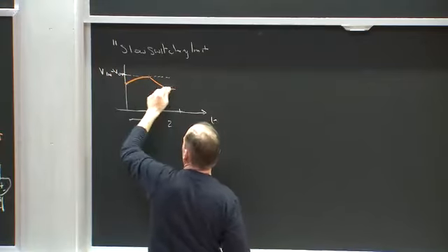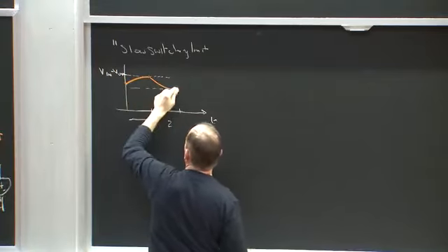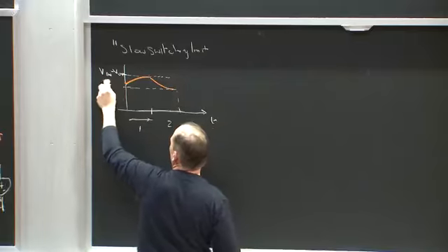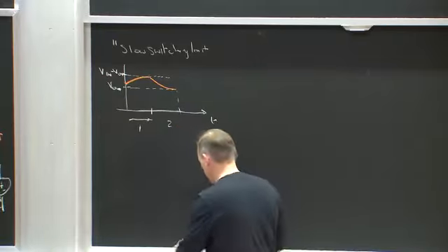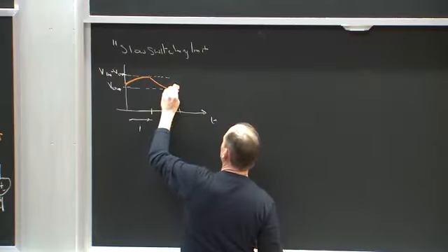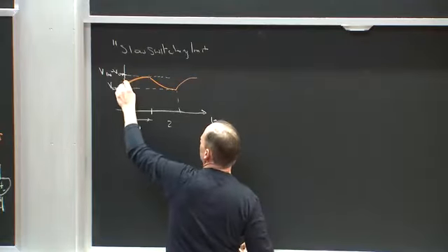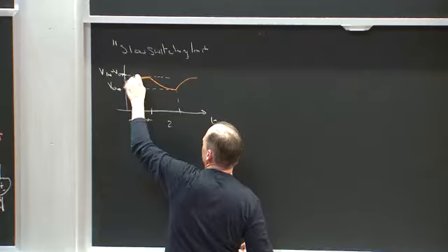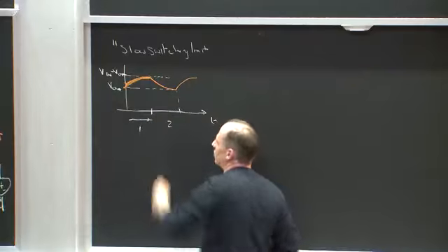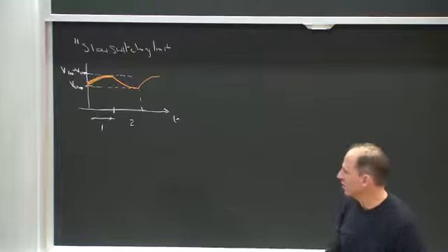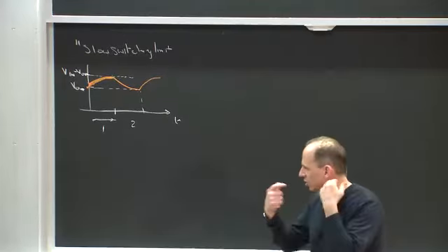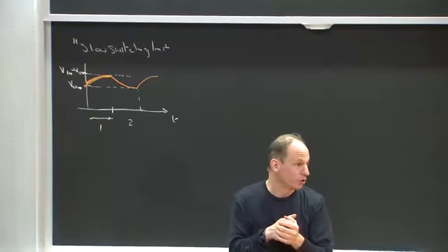And then in the next state, in state 2, it's going to charge to V out. Okay? So my only assumption is that each cycle I'm going to charge up and charge down, and I'm going to finish the charging. I'm going to let this RC time constant go to where it's fully charged. Okay? So let's think about how much charge I transfer in each component.